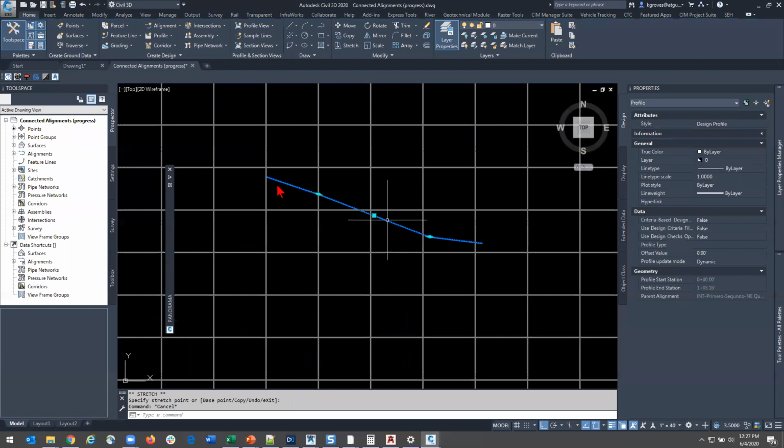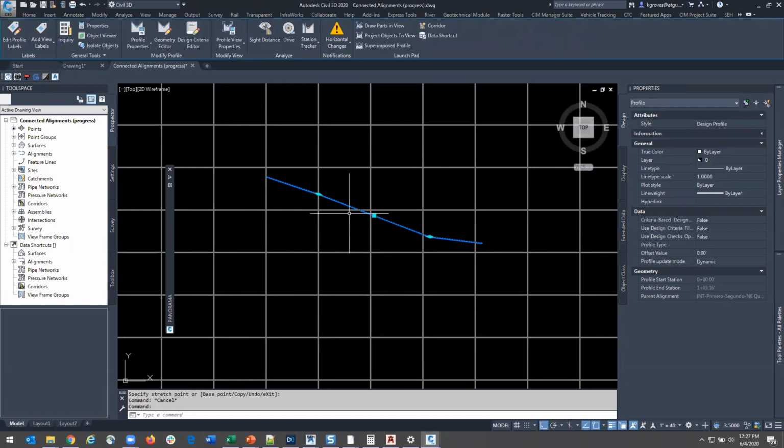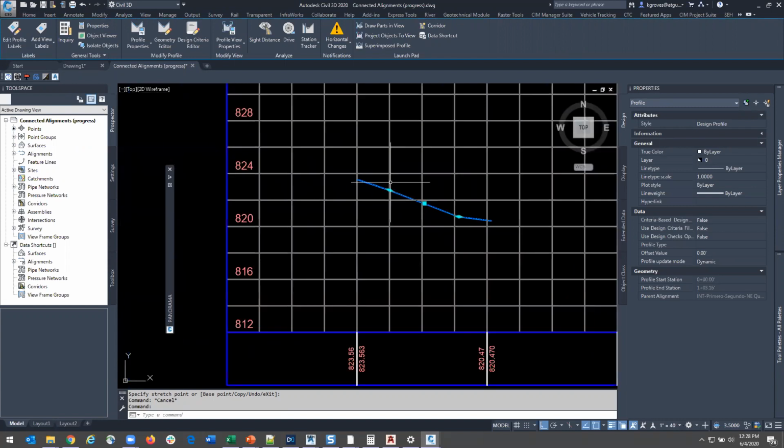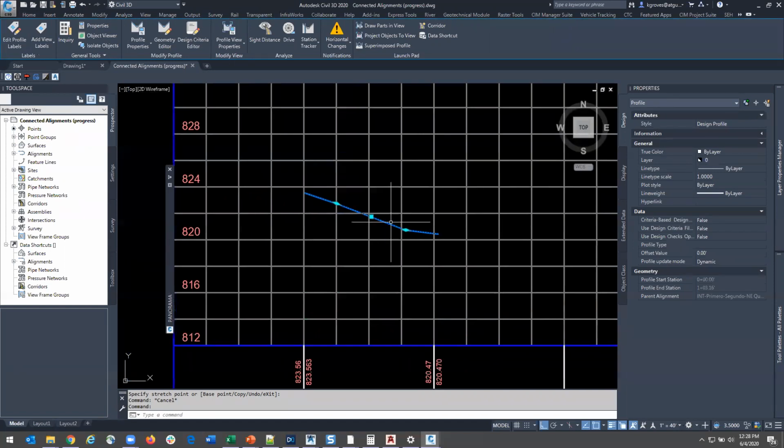And again, we can see that I have three sections here. Left and to this diamond grip represents my overlap. And notice how I chose a 25-foot overlap, and my minor grids are set up at a 25-foot spacing, so that jives, that makes sense. Then however long my curved section was, and then again, another overlap.